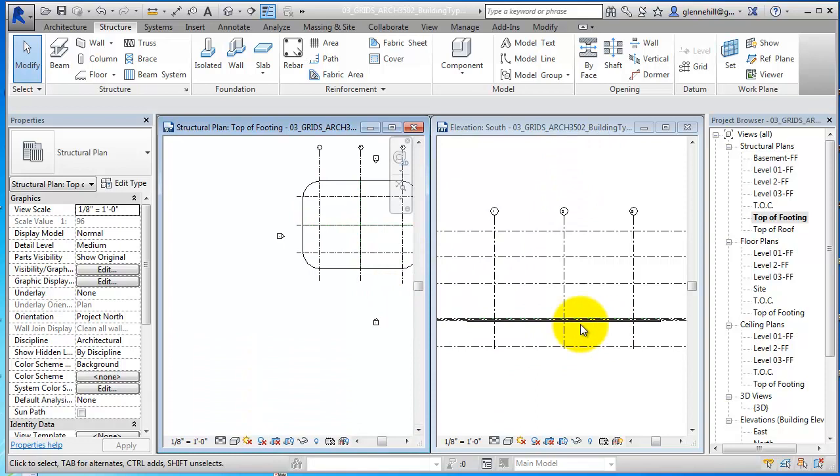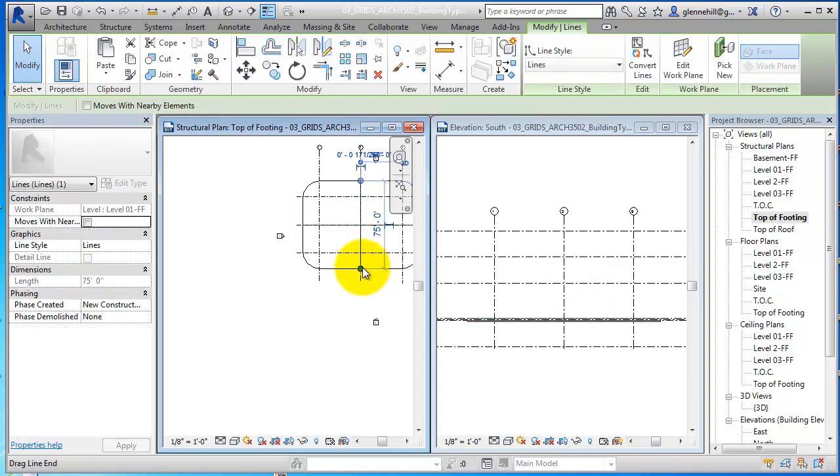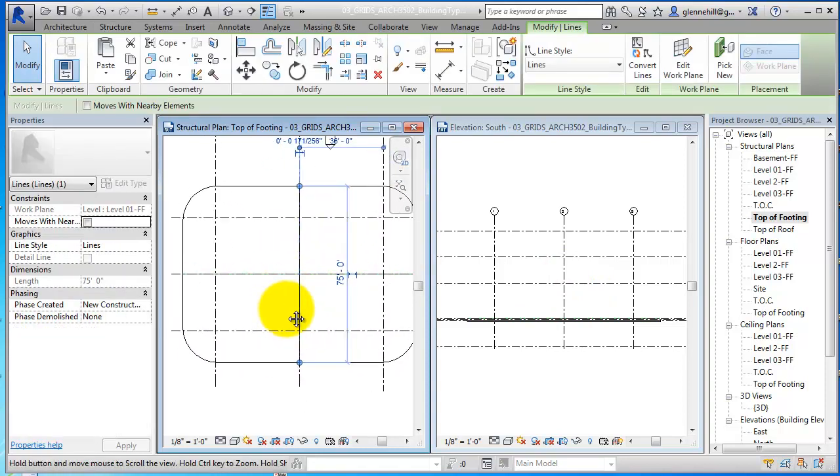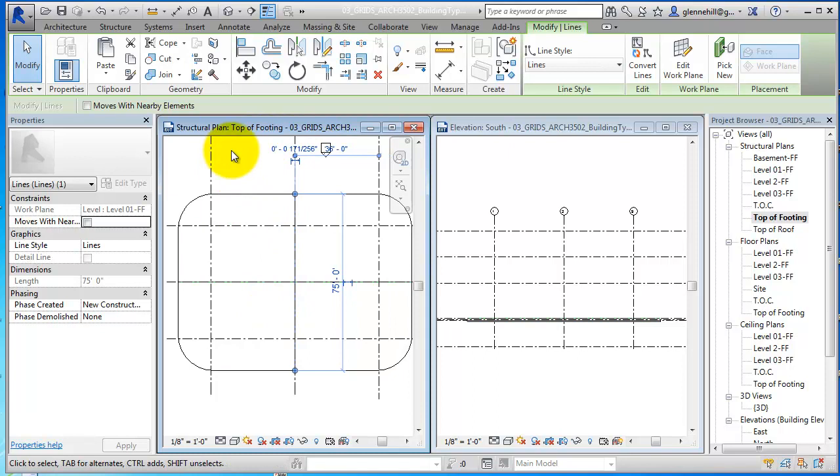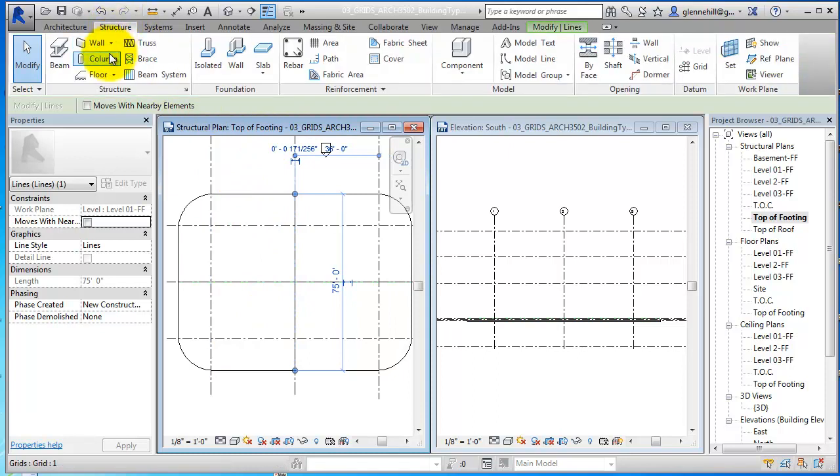and you'll see level 1, and you'll see top of footing, and that's the place where we want to place. So we're going to place it at the top of the footing, and then in its height to the first or the second level up here. Okay, so top of footing. So we open the top of footing. Let's go back now and Structure, Column,